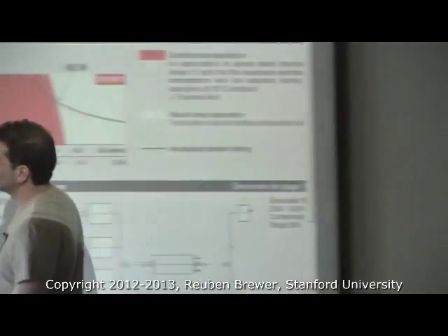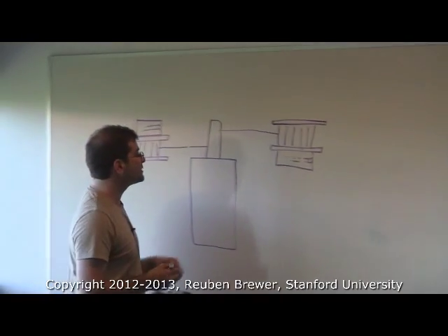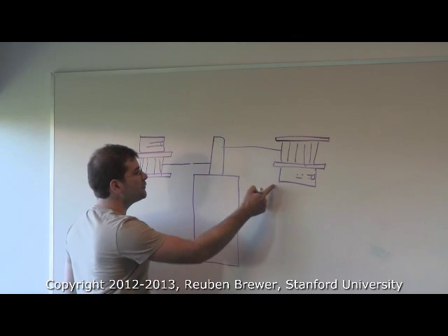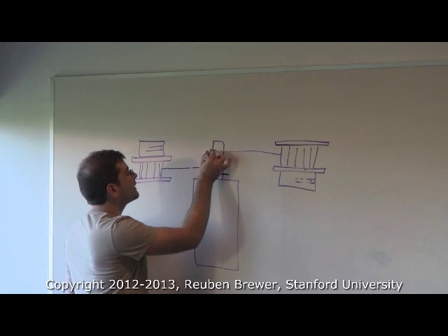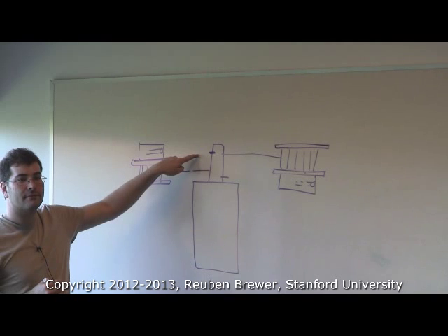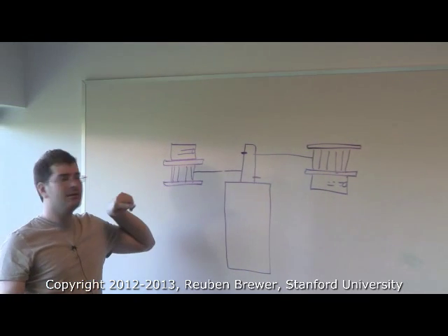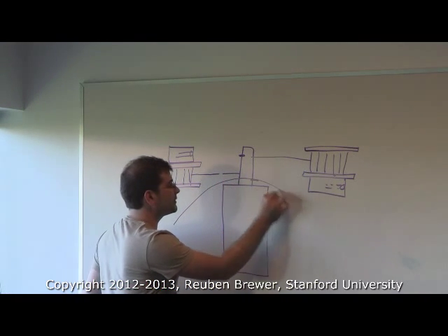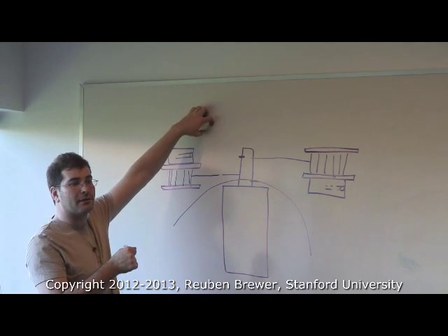What's another good reason, by the way, for this? These are set screws as I've drawn them, which means I have to put a flat on my shaft, right? And on this one, the flat has to come all the way down here. On this one, the flat only has to come right down here. So you have to Dremel less. Now, remember, I showed some of you over the weekend, when you're Dremeling on something nice, you're going to put a plastic tarp and duct tape everything, and you're going to have a vacuum up here while Dremeling.